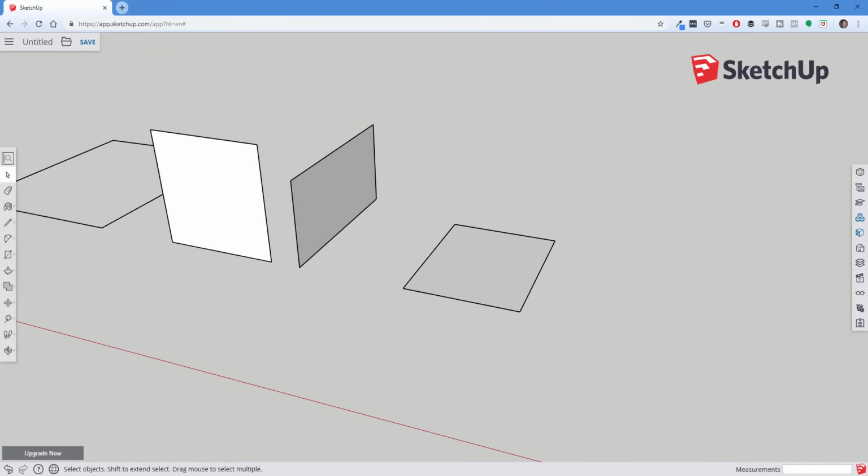And so in the remaining time, I want to talk about going to 3D inside of SketchUp. Let's say, for example, that I have this rectangle right here, and I want this to become not a cube, but more of a 3D rectangle. So you can see how what I'm doing is I'm coming in here and I'm drawing out all of these different edges. And by the way, to lock to an inference, you can hold the shift key in order to lock that along whatever your inference is.